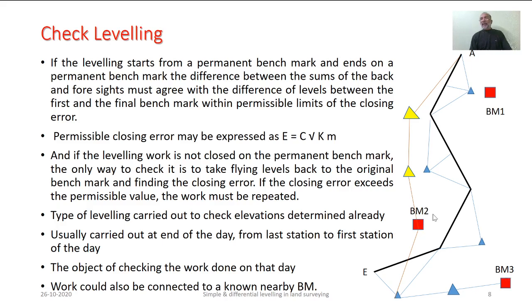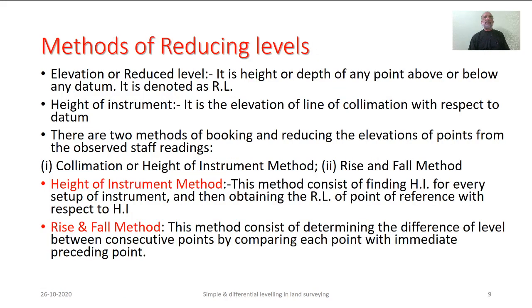Again, the value that we have and the value that we determine with respect to RL of last station should be in close agreement with each other. As the name suggests, check leveling is nothing but the category of leveling which applies a check on the kind of leveling work that we did.